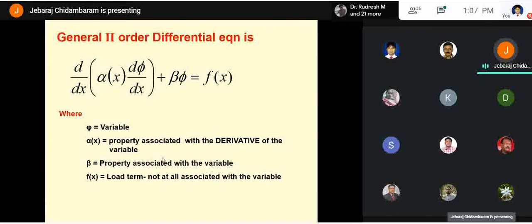Then you try to find an approximate solution by substituting an approximation, and a better approximation by satisfying the boundary condition. When you substitute that better approximation, your governing differential equation is no more homogeneous; it becomes not equal to 0, there is a residue. You minimize the residue by the Ritz method, that's your energy equilibrium. So the solution is going to be the energy equilibrium, which makes it the best solution. So finite element became the best approximation.